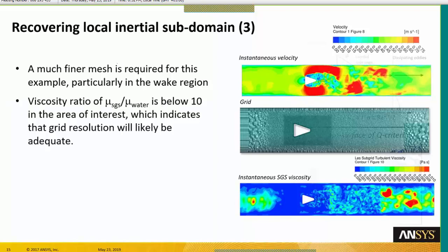And here, once again, if you place a probe here in the refined region, you will see that the velocity spectrum is showing something much nicer. We are close now to the Kolmogorov inertial law, k to the power minus 5/3. It's clearly an indicator that things are going better, and you see that you are capturing a larger number of eddies, and these eddies are dissipated at the correct rate.